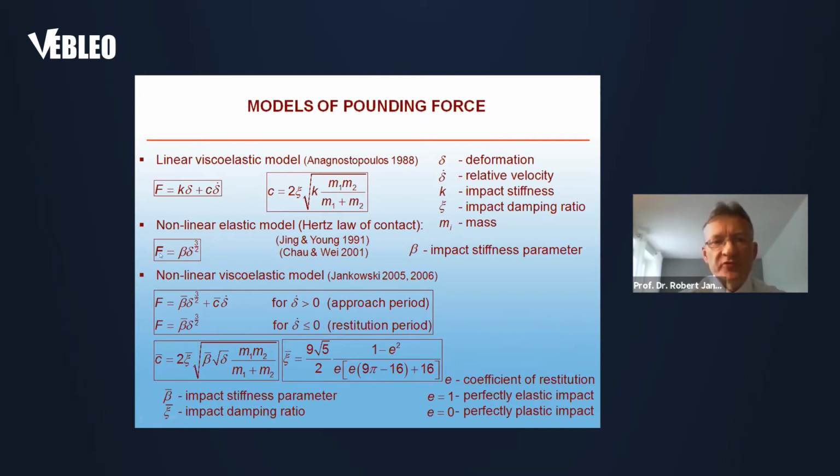In order to model the relation between the force and deformation, the nonlinear elastic model following the Hertz law of contact is often used. However, the drawback of this model is that it does not account for the energy dissipation during contact, because this is a purely elastic model. In order to overcome this disadvantage, the nonlinear viscoelastic model was also proposed, and this model combines two different equations, one for the approach period and one for the restitution period.